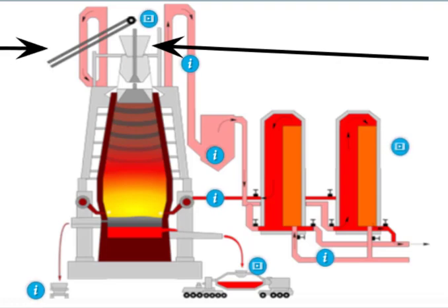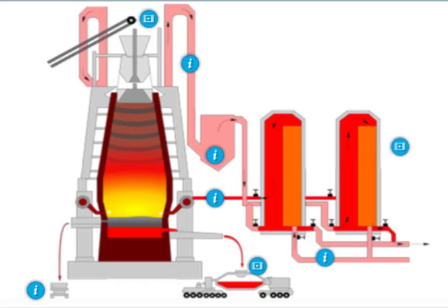The raw materials may be stored temporarily in the stock house where the furnace burden is prepared, called the BHS, burden handling section, in steel plants. Each type of ore, pellet, sinter, coke, and limestone is dumped into separate storage bins. The various raw materials are weighed according to a certain recipe designed to yield the desired hot metal and slag chemistry. The weighed materials are then transported by conveyor belt to the charging conveyor.